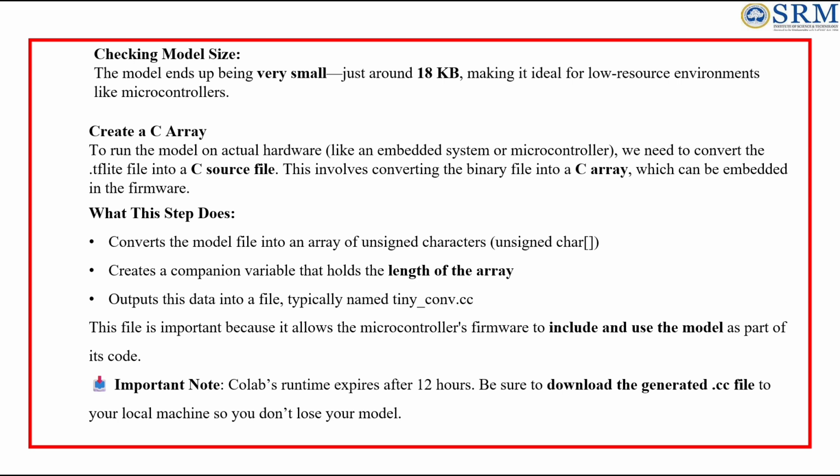Key details. The input and output files are specified, and the settings used during training, and the input shapes because we are dealing with one input sample at a time. Checking the model size, the model ends up very small, just around 18 KB, making it ideal for low resource environments like microcontrollers.